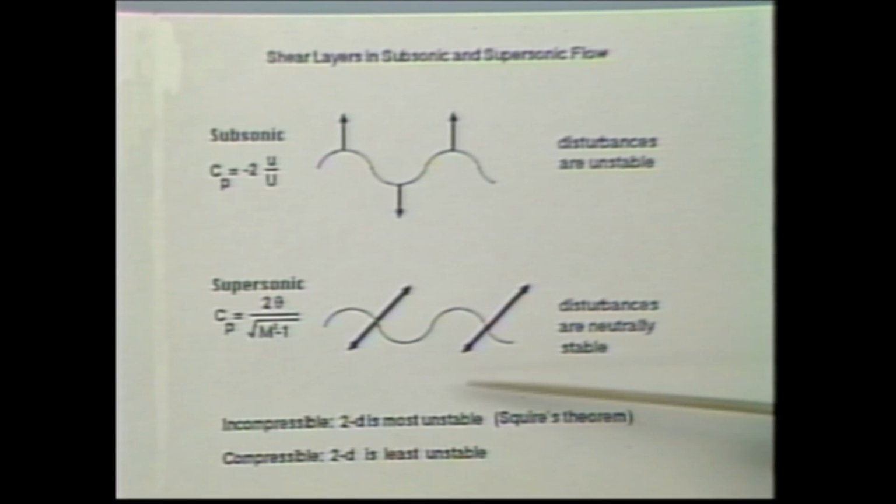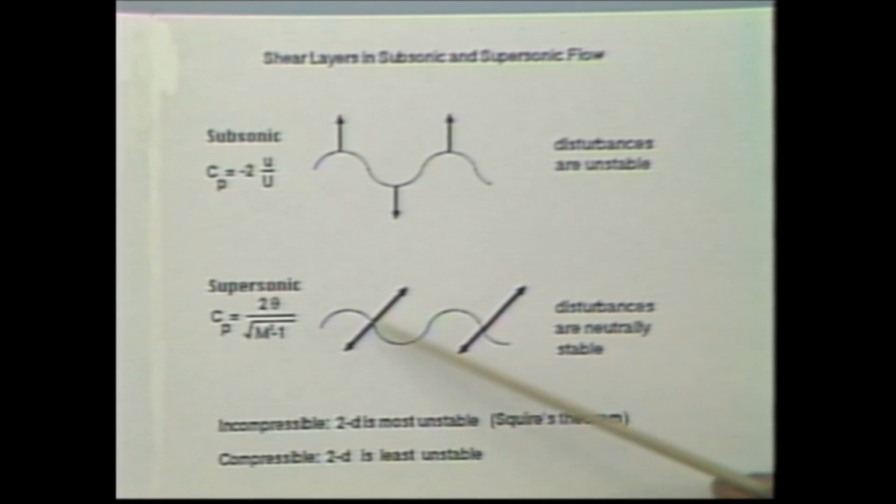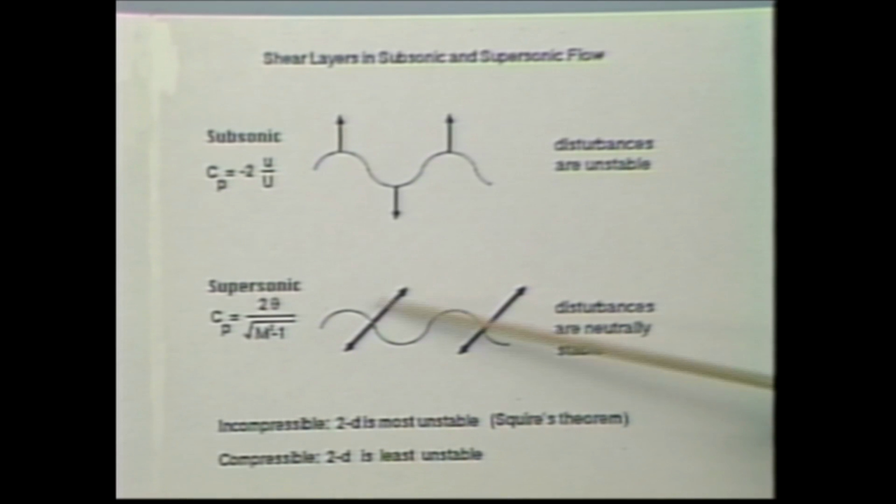And now those two flows are moving at a relative supersonic Mach number. So from the point of view of those flows, that disturbance might as well be a wall. Well, the maxima and minima of pressure line up on either side of those disturbances. In other words, in supersonic flow, there is no trend to amplify the magnitude of that disturbance.